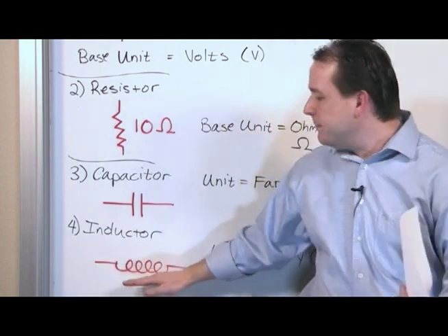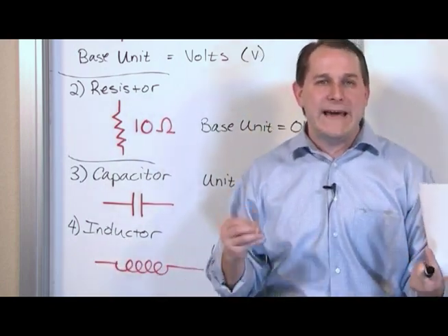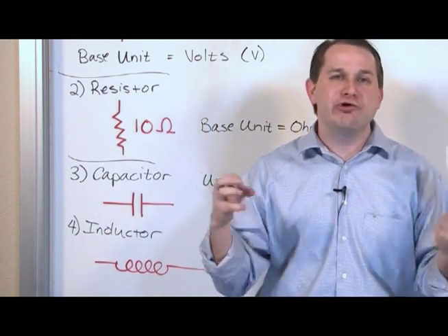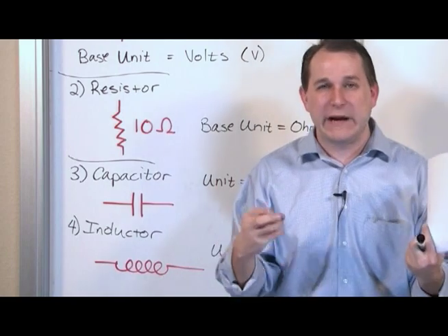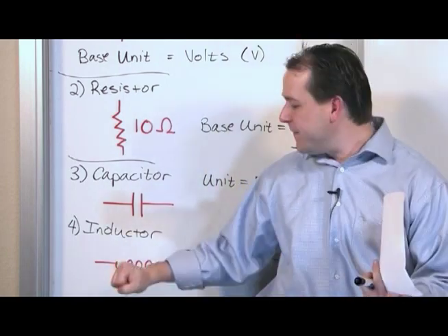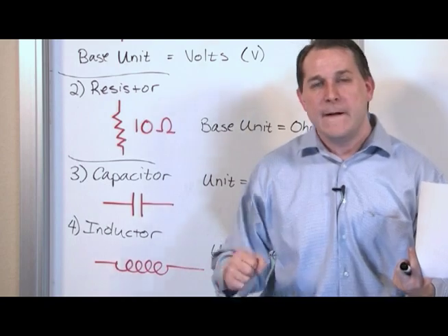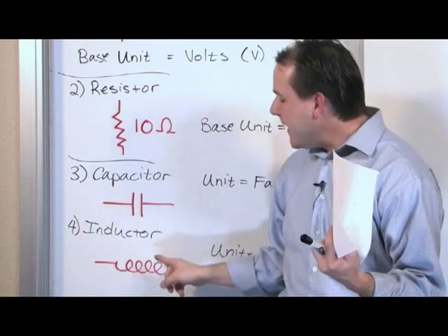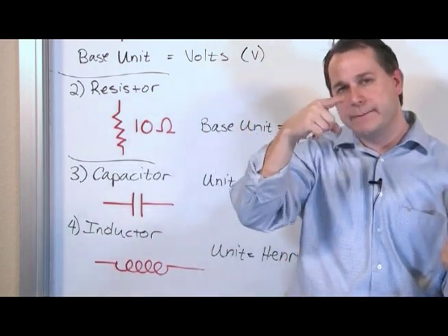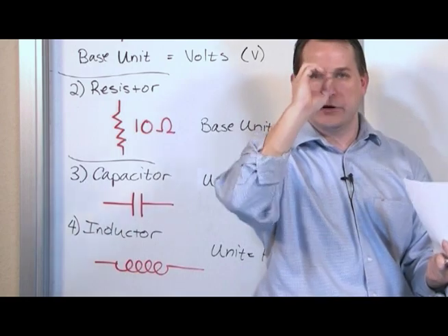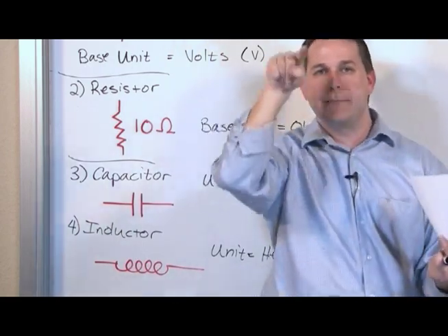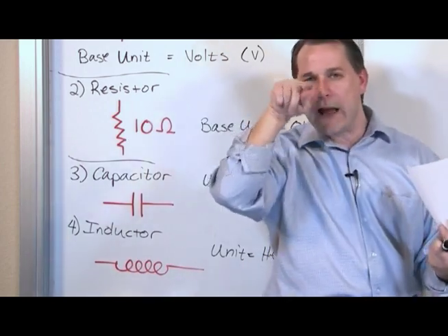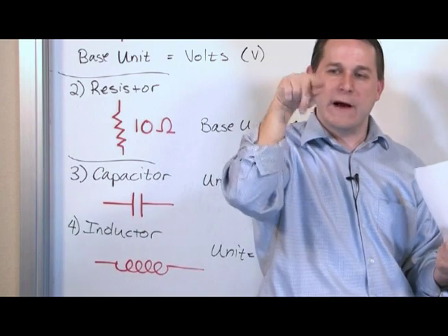So what we try to do when we construct an inductor is we try to make a device, and this is important, that will concentrate that magnetic field and make it stronger so that we can store even more energy inside that magnetic field. And that is exactly what an inductor actually does. Because if you take that wire and you look at its magnetic field, it goes around the wire. But if you take a wire and you coil it up like this, then think of a cylinder coming from me to you, and I take a wire and I wrap it around the cylinder, like a paper towel tube or some kind of pencil maybe, and I wrap a tight wire around this cylinder.